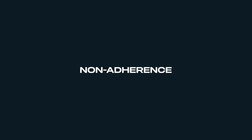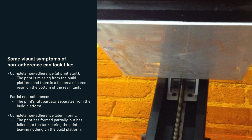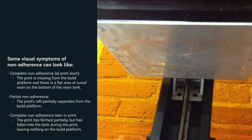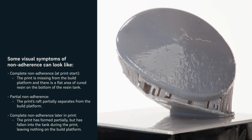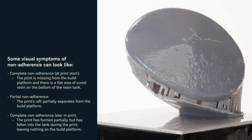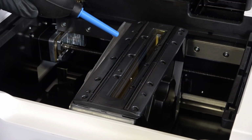Non-adherence describes a print defect in which prints are either partially or completely detached from the build platform. This occurs when the initial layers of a print fail to adhere to the build platform. Some visual symptoms of non-adherence can look like complete non-adherence at the start of a print, where the print is missing from the build platform and there is a flat area of cured resin on the bottom of the resin tank. Partial non-adherence, where the print's raft partially separates from the build platform, and complete non-adherence later in the print, where the print has formed partially but has fallen into the tank during the print, leaving nothing on the build platform.